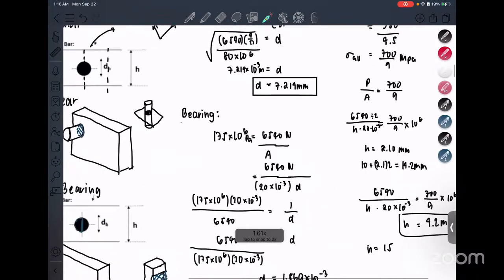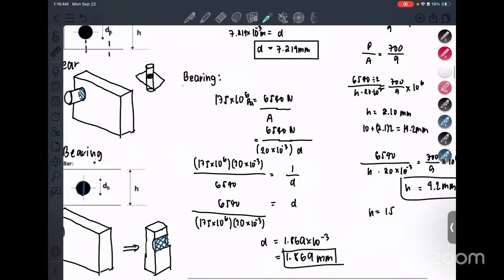So you have two options. Again, for plug size, usually you pick the larger one, because if you plug this into here, it can handle the maximum bearing stress. But if you plug this into here, there's no guarantee. It is very likely that the thing will fail. So we picked the larger one.